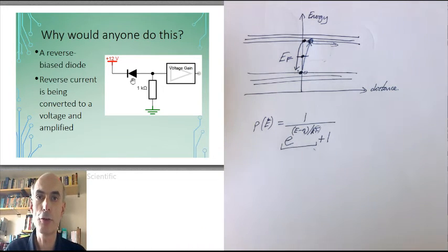You can buy components specifically designed to do this. They're called photodiodes. In fact, any light-emitting diode will work as a photodiode. If you put it in reverse bias, the saturation current that you will get out, the small reverse current, is a function of how much light is shining on the LED. But if you want this function, it is rather better to use a specially designed photodiode.